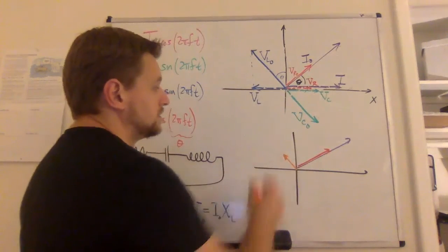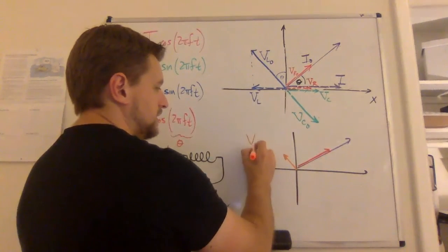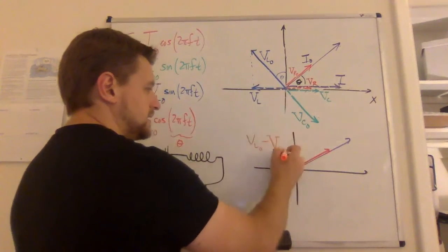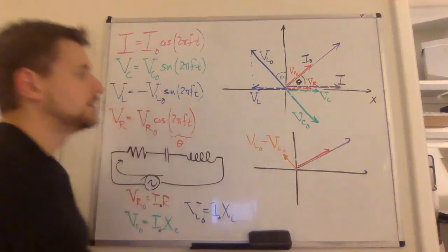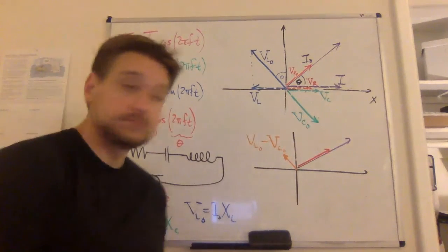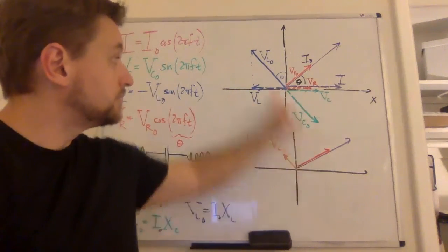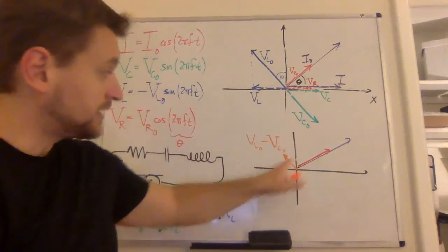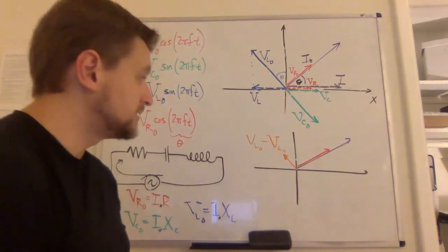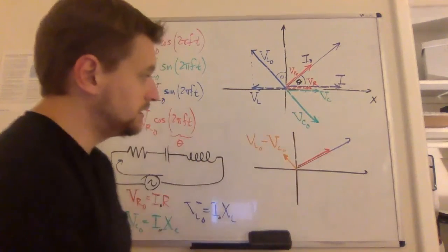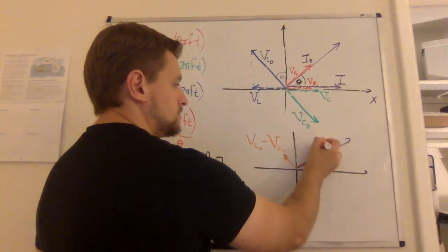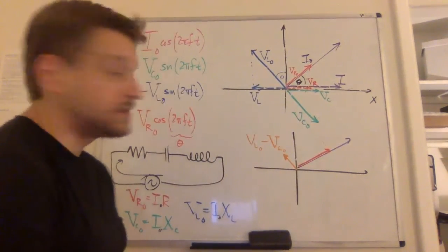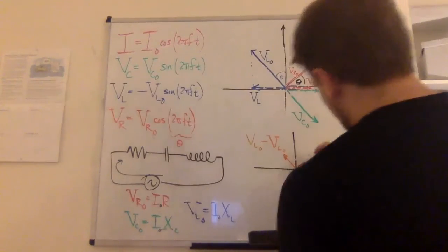This vector represents VL minus VC. And it's perpendicular because these are both perpendicular to the resistor. Now we've got two vectors. We can add them. We just put the one over here, and the result, add all these colors together, it looks something like brown.